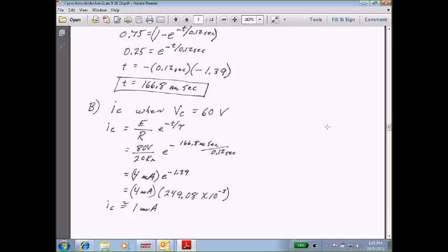Yeah, we also use them for filtering. Okay. When you're converting AC to DC, just a typical DC power supply, you've got ripple. If you were to look at that DC voltage level, you've got ripple in there. So what we do is we use a capacitor to fill the gap, so that on that negative cycle, the cap's actually going to charge that up, and we end up with a DC flatline coming out rather than a DC flatline with a little bit of ripple riding on it. Sure, that makes sense. That's how we filter that out. That's another application that we use them for.